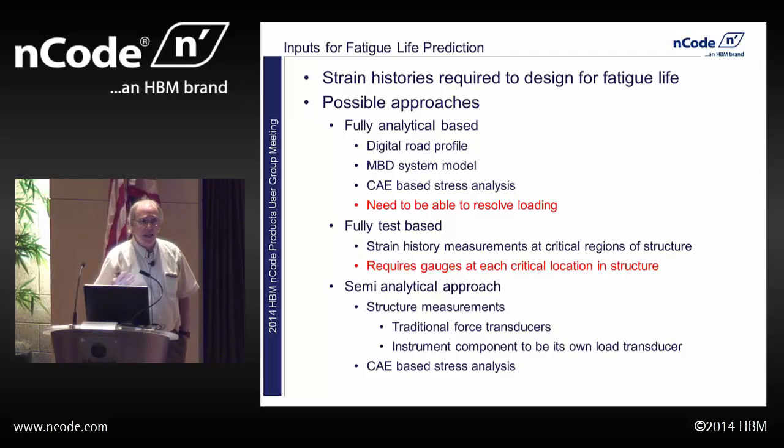One, we could take traditional force transducers and introduce them into our structure. Or two, and what we're going to focus on, creating specific strain gauge measurements so that we can turn whatever component we're interested in into its own force transducer. But once we have load measurements that we can pull out, we can bring those into DesignLife into our fatigue analysis, and again, use that to generate the strain histories downstream.